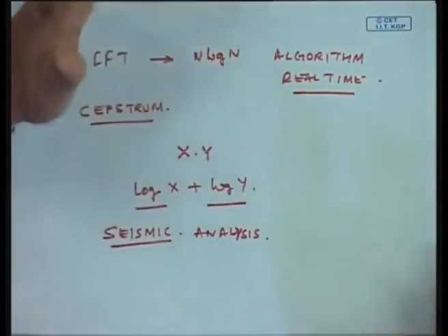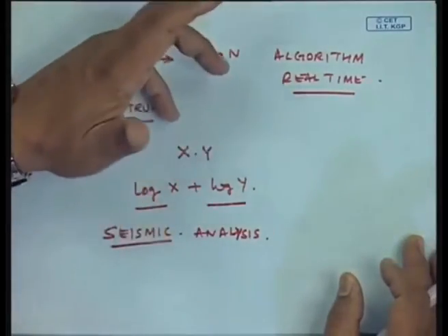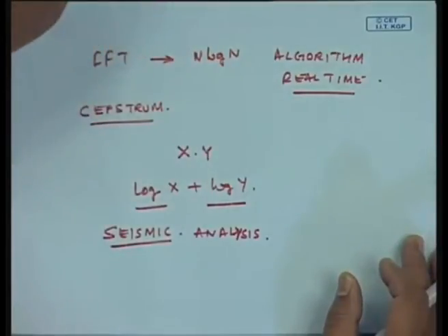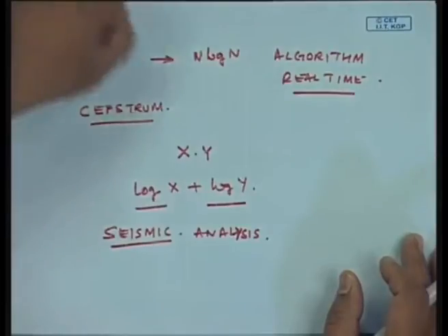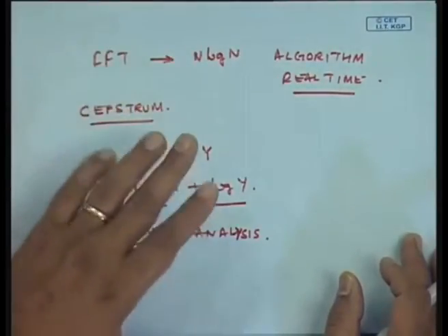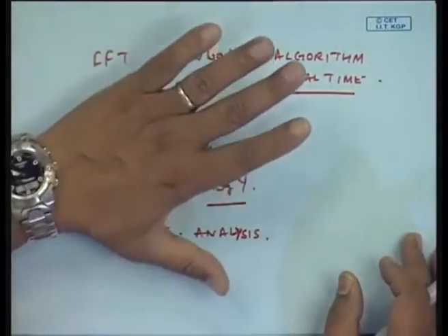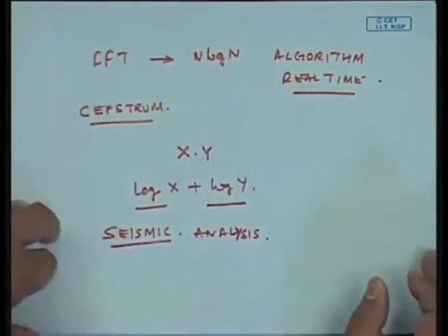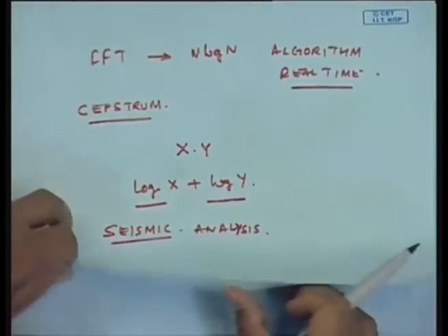Here we will see the same also happens. Suppose I have a large gearbox, a lot of signal contamination occurs because of the path, whether it is coming from bearing A or through bearings A, B, C, all those effects will be lost or easily removed once we do Cepstrum. So, to summarize, Cepstrum is a powerful method to find out sidebands in modulated signals.